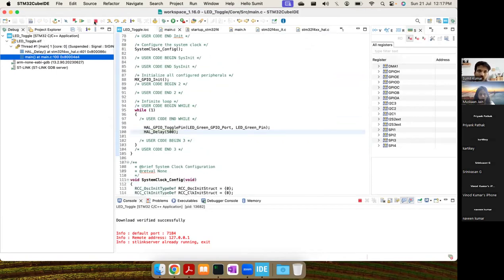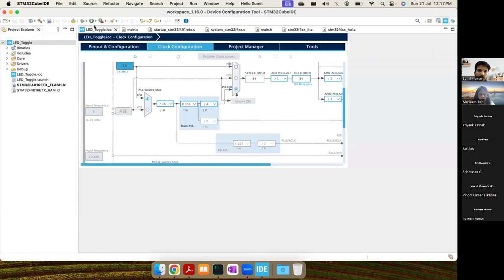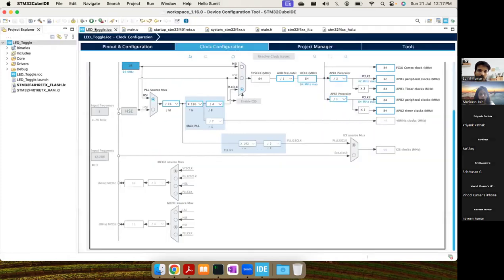All right. So we have the first method done, how we generate code with CubeMX, but I don't use it often. What I prefer is to directly import some examples and then start working from there. ST provides different kinds of examples for each peripheral, and you can directly import those examples and start working on them.